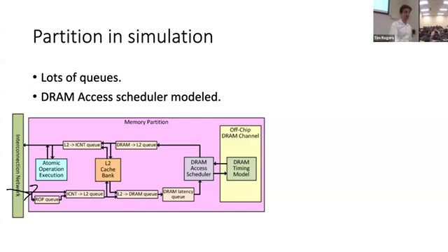If it's an atomic, then you'll potentially have to go into this ROP queue to do the raster operation. If it's not, then you don't have to do it. You can potentially bypass it. We actually have profiled things, and it seems like all of the accesses go to the ROP queue because the latency here is way higher than what you might expect. L2 latency in GPUs is super high, and it's probably because they don't mess with it to try to make it better for latency.